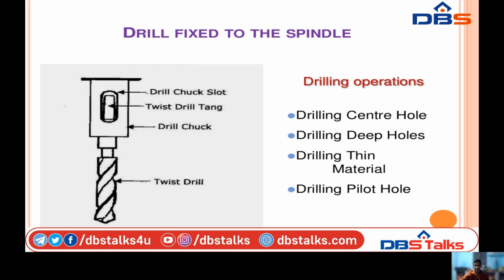Next, drill fixed to the spindle. In this, I am showing that the drill bit is fixed to the spindle. In the middle section, I am showing the lock. We can fix the shank of the twist drill to the spindle in the center of the chuck slot. Drilling operations include drilling center holes, drilling deep holes, drilling thin material, and drilling pilot holes.